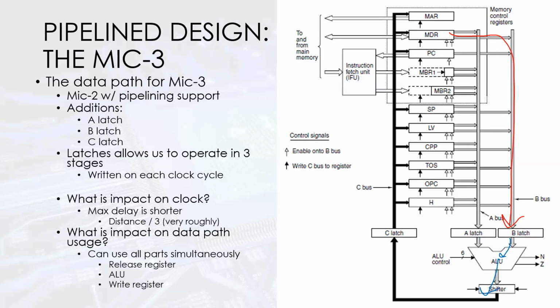Let's say that ends up being 10 nanoseconds and this was 5. Then what that essentially means is we're just going to let this data sit there for 5 nanoseconds. It's going to be pounding at the door, just waiting, let me in. As soon as the ALU makes it to here, which maybe is 10 nanoseconds, at that point we would hit our clock cycle and all of those gates would open up. Is that kind of what you're getting at?